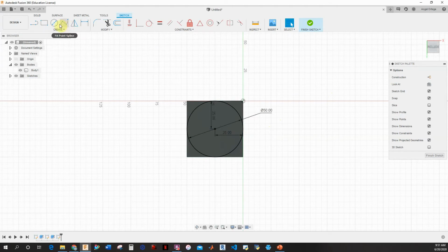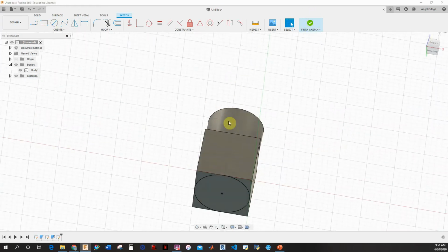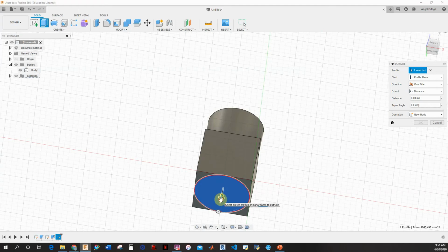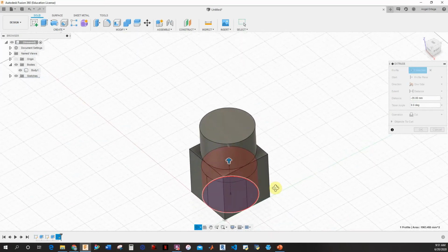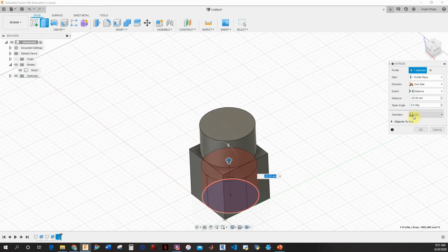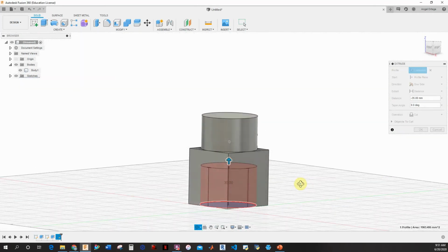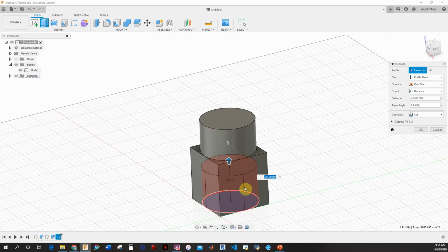Then I'm just going to extrude. I'm going to either type E or finish the sketch and look for extrude down here. Then I'm going to go into the material. How much? It all depends. So maybe like 35, 30, I don't know. As you can see, it's now automatically trying to select a cut operation, and it highlights that volume in a gray red color, depicting that you're trying to remove it. So I'm going to hit OK.